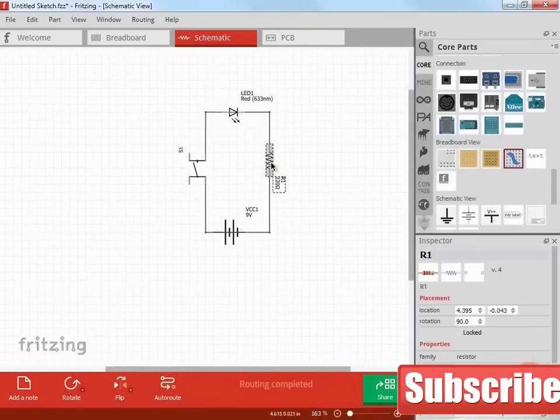And the resistor is the one that we have to select in order to get the proper current flow characteristics through that diode. We had already mentioned we're going to use a super bright LED, which is quite functional at 20 milliamps. So using Ohm's law, the 9-volt battery, we need to calculate the value of the resistance.